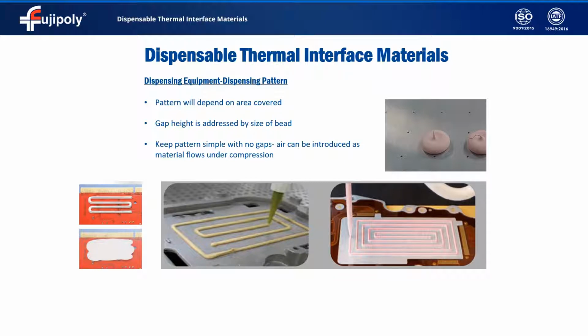And you'd like to cover as much of that area as possible to make sure that you have the best heat transfer available. It's better to keep the material close by when you're dispensing. If you have a larger surface area and you need to dispense some kind of a pattern rather than just a blob in the center, you'd be better off keeping the pattern tight so that you don't introduce too much air, because air will impact the heat transfer.